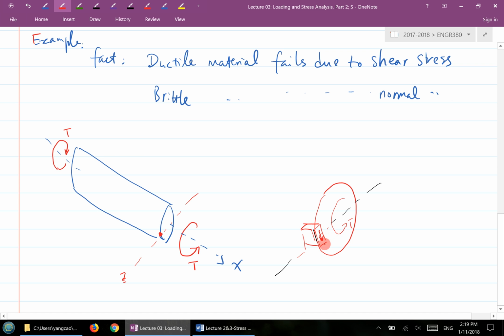And then you can extend this stress element to a cube. Then supplement this cube under the assumption of equilibrium. So basically you would have a shear stress pointing that way on this side here, and the other sides are all going to be empty. Also, of course, at the bottom and the other side, but two sides is fine. Again, this is a planar state of stress. If I look at the front view, the front view will give us a state of stress, which is this. Technically speaking, these two sides should be supplemented like that to make equilibrium.